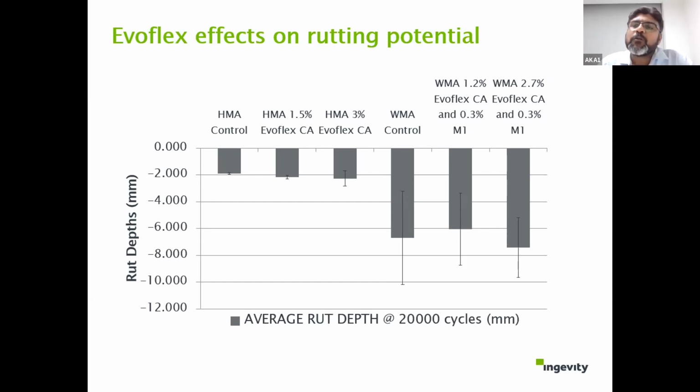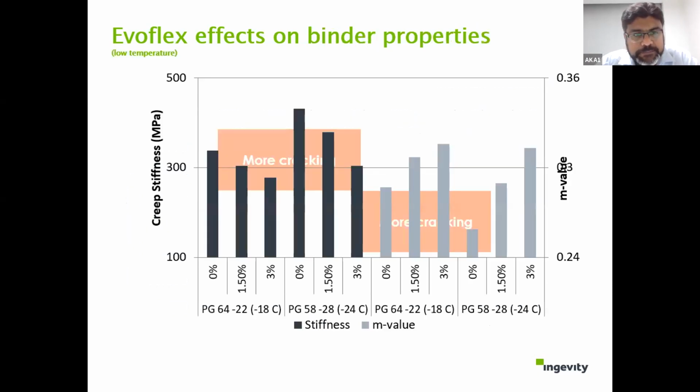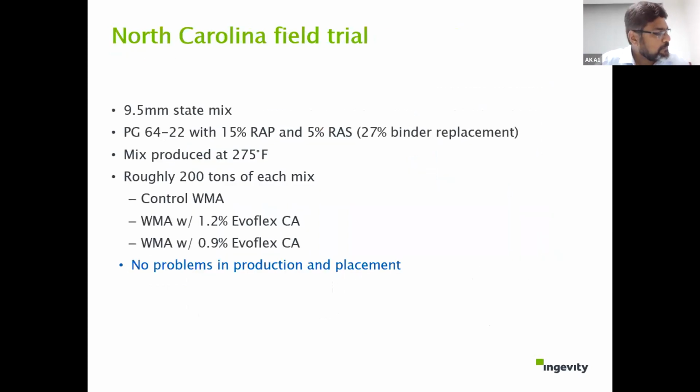So they want to fix these combinations. Various studies are going on from this perspective. Again, cracking is a major concern, especially at low temperatures and in cold weather countries, so a few more studies and data on those. There is a project that we did in North Carolina, again a combination of warm mix and different rejuvenators. You add different rejuvenators and see what happens at different dosages.